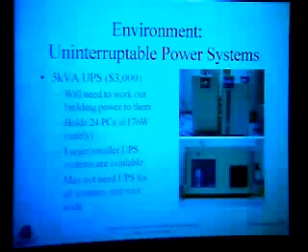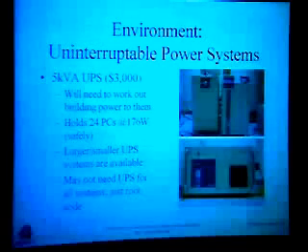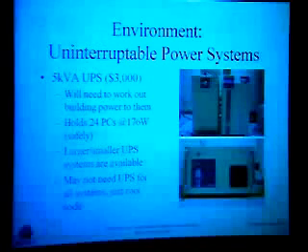You're also going to want to have some kind of uninterruptible power supply, a big battery. If you just buy one, you're probably going to have to work with your building people to get it actually plugged in. They run on 220 more of the time. For a 5 kVA UPS, it's going to be able to hold about 24 PCs of the same wattage. They've got bigger ones, they have smaller ones. We've tried lots of things. But if you want to save on that, you can just put your root node on the UPS. This is for one style of cluster, which will be discussed more by John in a bit.